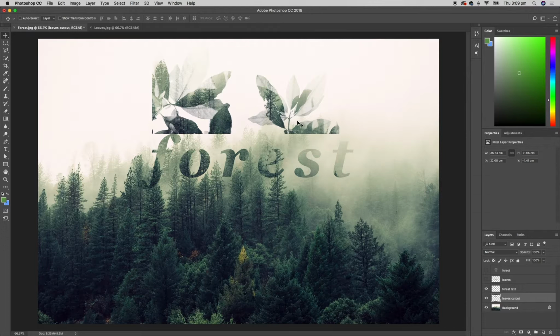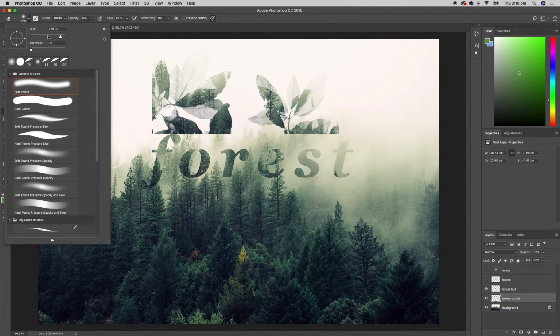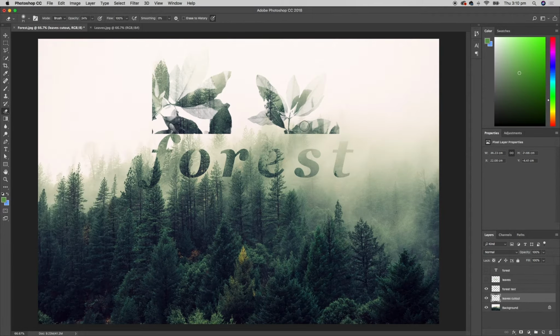Now there's some parts of these leaves that have the sharp edge on them. I'm going to erase those just by hand. So let's go to the eraser tool. And if your eraser is too large, go up to the top, and you can hit this down arrow and change the size. Let's say 111, maybe a little bit smaller. 70 looks good. And you can choose hard round, which will give a crisp edge, or soft round, which will give a much softer edge. We'll use soft round.